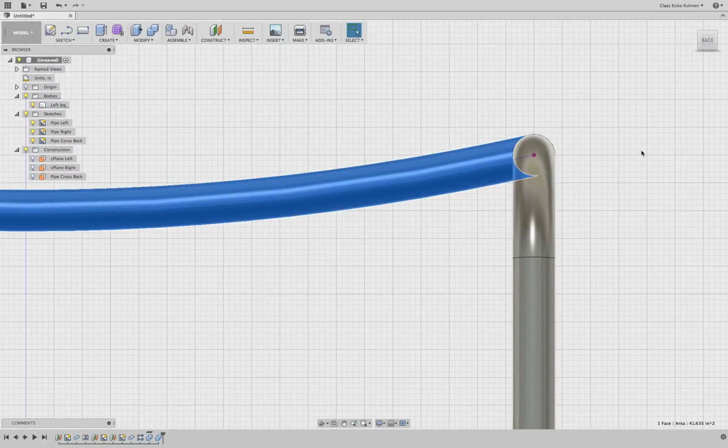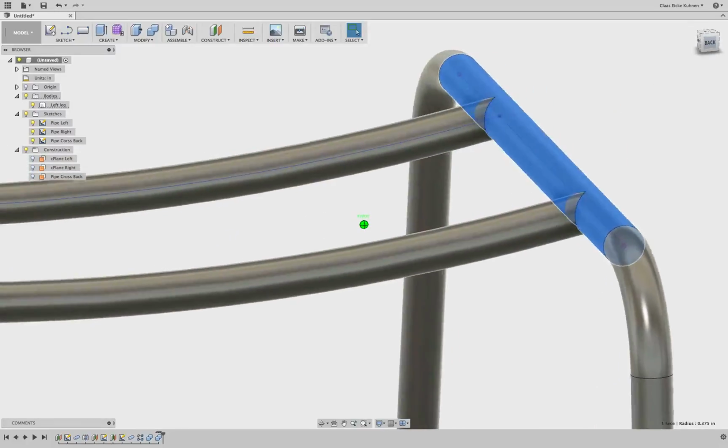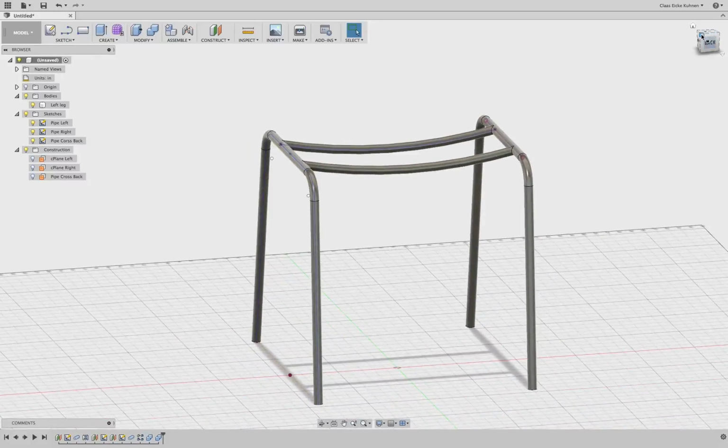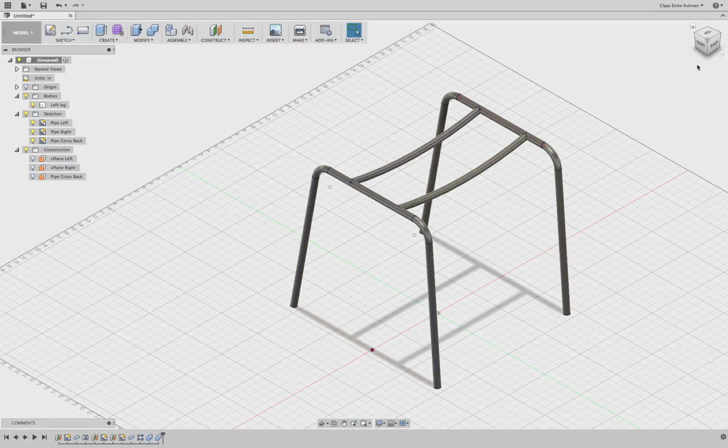So we would have to grind this out, so we could put it nicely onto this pipe, and then we have nice touching edges and we weld it. But again, since we're just exploring a design idea, we can just build it the way it should maybe look later. And then the correct manufacturing data we can later still regenerate. That's a nice thing about Fusion.